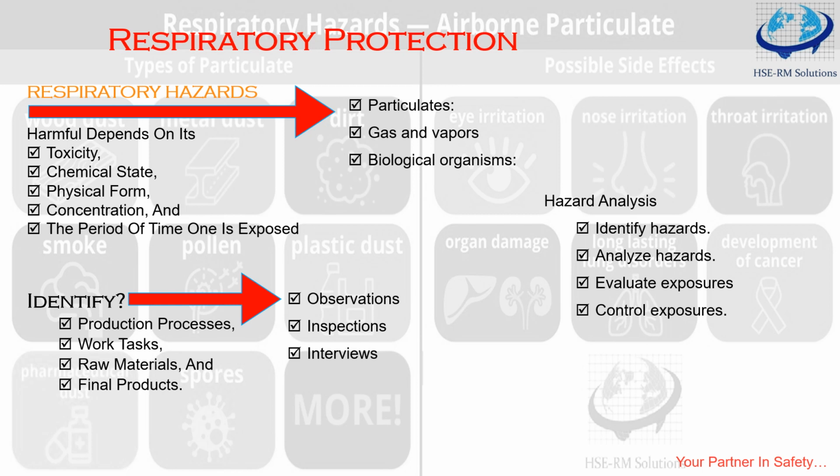Now, there is another factor called maximum use concentration, MUC. Maximum use concentration means the maximum atmospheric concentration of hazardous substances from which an employee can be expected to be protected when wearing a respirator.